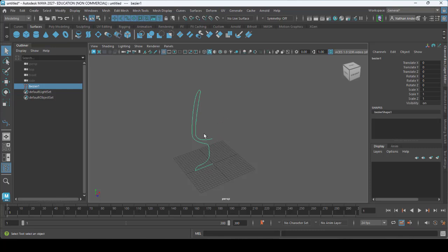And so the other part will fill in this back section, leaving an empty space in the middle. You want that. You want your shapes to have nothing overlapping in the center. We'll talk more about good topology at a later time. Under surfaces, I'm going to click on revolve.